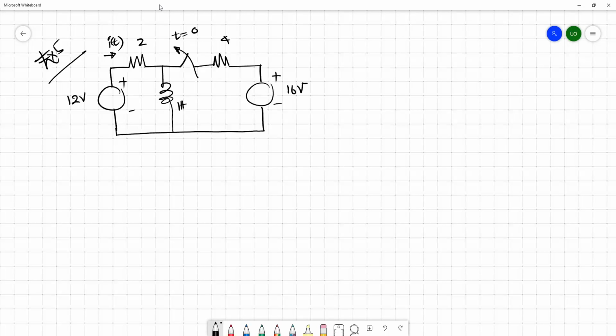Okay, the circuit question explained that assuming that this circuit has had sufficient time to go to DC steady state prior to t equals 0, determine the response of the inductor. So we found that we don't have the initial condition of the inductor, so we need to find the initial condition of the inductor as well to find the exact response of this one. Then we'll go to t less than 0.